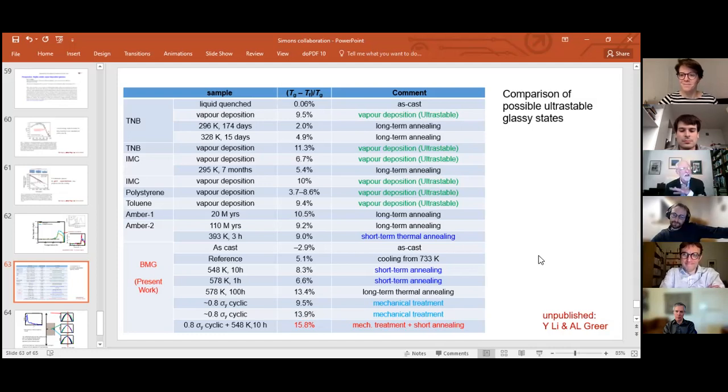In order to get to lower energies, they use lower and lower deposition rates. And they have not paid sufficient attention to the fact that, of course, your sputtering is never perfectly clean, and you get an outgassing of species from the chamber walls. I am, of course, thinking principally of oxygen. At high deposition rates, that's not that important, but at low deposition rates, it means what you're actually depositing is a metal oxide. Now, I put that in extreme terms, but you might have a few percent of oxygen in your deposit. For sure, that's plenty enough to affect the properties, possibly in a favorable direction, but it's not the metallic glass you thought you were looking at, is my point.